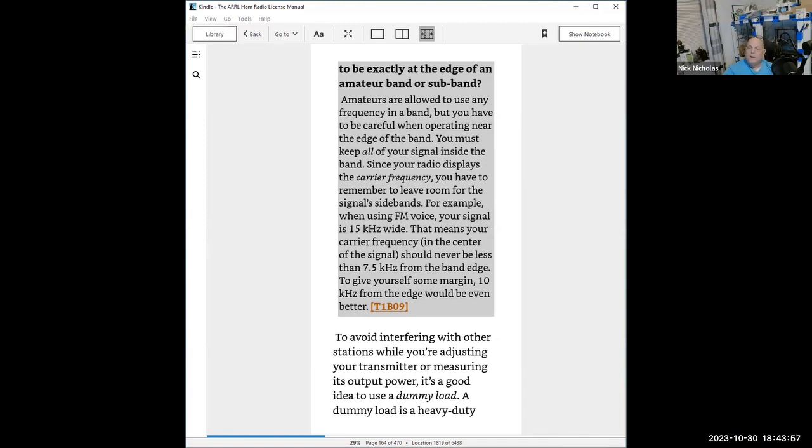Because of that, to a 50 ohm transmitter, a 50 ohm dummy load, which is a 50 ohm resistor of sufficient wattage to handle the load of the radio and then some, hopefully. You don't want to use too small a resistor, you will smoke it. Even a small dummy load on a high powered transmitter or amplifier is not a good plan.